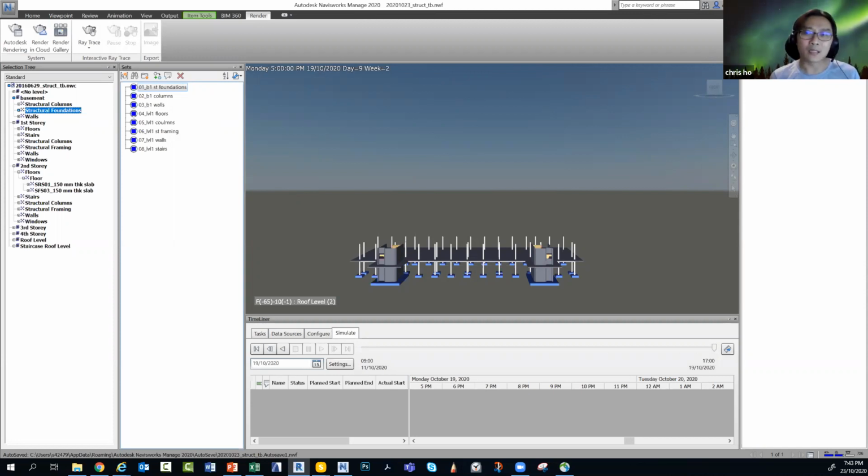But with SMC, you have to export your model as IFC. If you have Autodesk products like Revit, then obviously you have to export it to IFC. And when you export to IFC from Autodesk, it takes at least a few hours. If your project is very big, it will probably take 1 day. Converting it to IFC can also result in your model not being exported properly. For example, you have a facade, but when you export it, it might end up faceted, which is not what you want. These are some of the disadvantages if you are using SMC and coming from an Autodesk product.